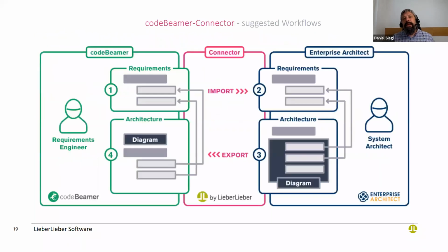So what is the typical workflow between requirements engineering tool and modeling tool? The typical workflow is that you can import requirements. I have to warn you though, in most cases, you only import the requirements and not necessarily the traceability links that have already been created in the ALM system. In our case, we bring also the connections between, for example, customer and system requirements into the modeling world, which gives a lot of extra benefits because you have the full information available also in the modeling solution.